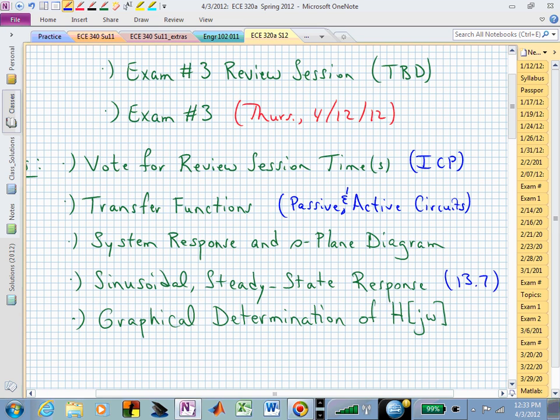So you shouldn't be expecting anything weird to be happening if you have a linear time invariant system. If you shake it at omega naught, your outputs, wherever those are or whatever those are, should be at the same frequency omega naught. What may be different is the amplitude of that sinusoidal response and its time relationship or phase difference between your input excitation and what you're measuring at the output.